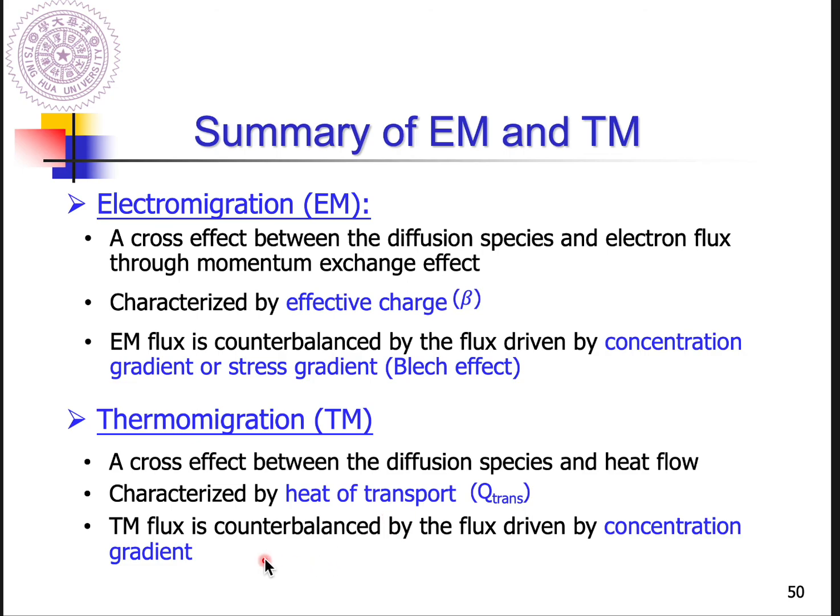And by the way, are there any possible driving forces that can counterbalance the atomic flux driven by temperature or temperature gradient? Yes. The concentration gradient is a possible driving force to counterbalance this flux, and the vacancy flux also has a chance to counterbalance the atomic flux driven by thermal migration. Okay.